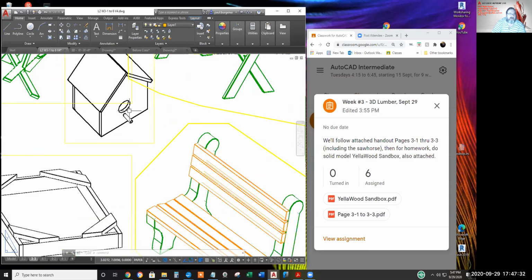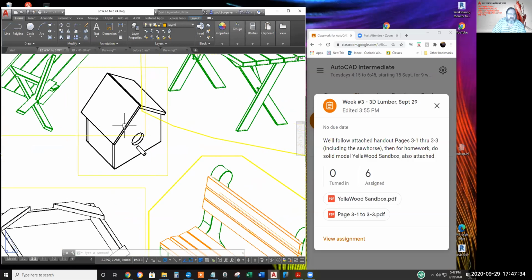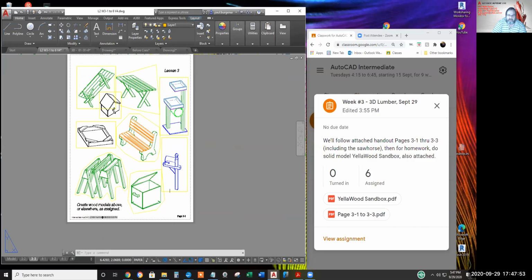I think you can do this simple birdhouse now by using the 3D rotate command. Make the roof panels on the XY plane and move them and 3D rotate them and then slice the boards that they nail to. Anyway, let's move on to the Sandbox exercise.